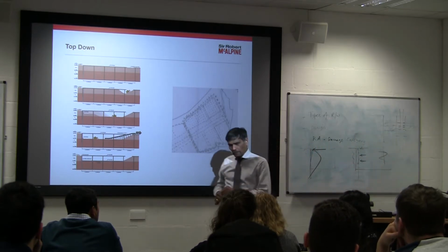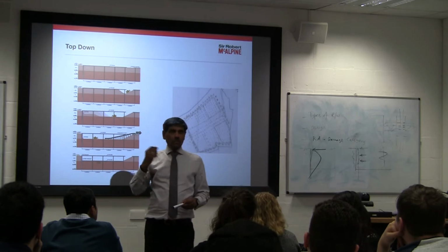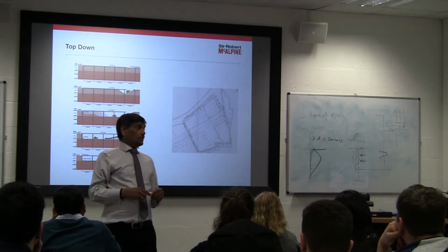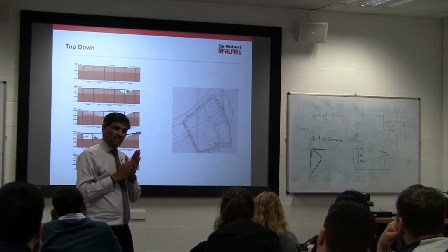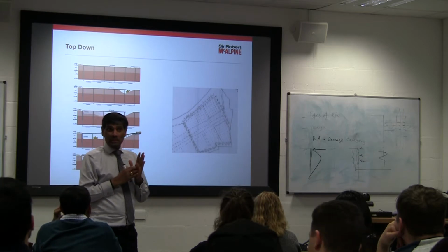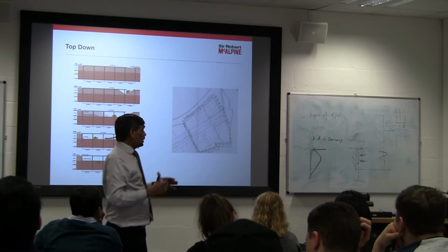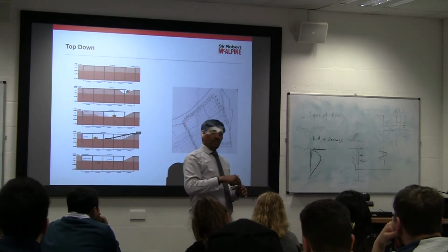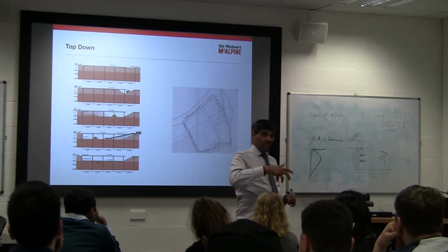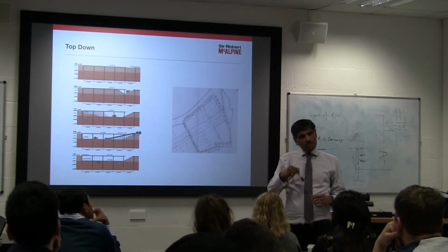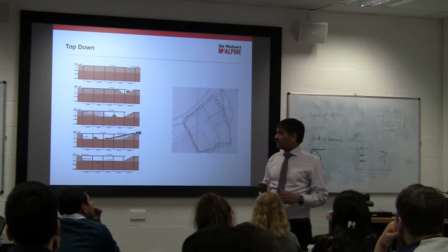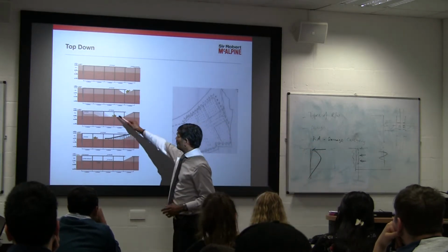So yes, it is very difficult to control the plunge columns, and if they go out of alignment, you quite rightly say that we must get the floor connections within tolerances of no more than 10 millimeters. Because it is a steel column, and because we've got a template that goes into the casing, that is how they control the tilt of it, and the longer it becomes, the more difficult it is to control. So that's another thing, we can't have a plunge column that is very long.